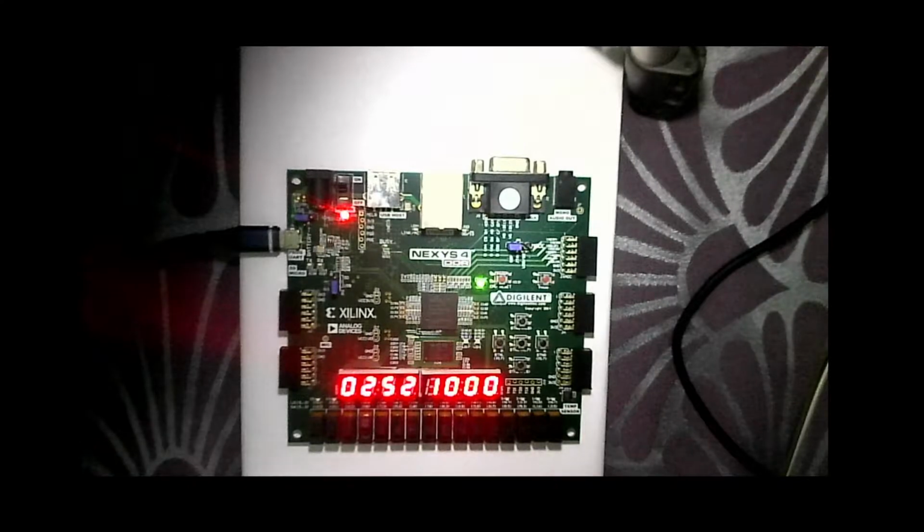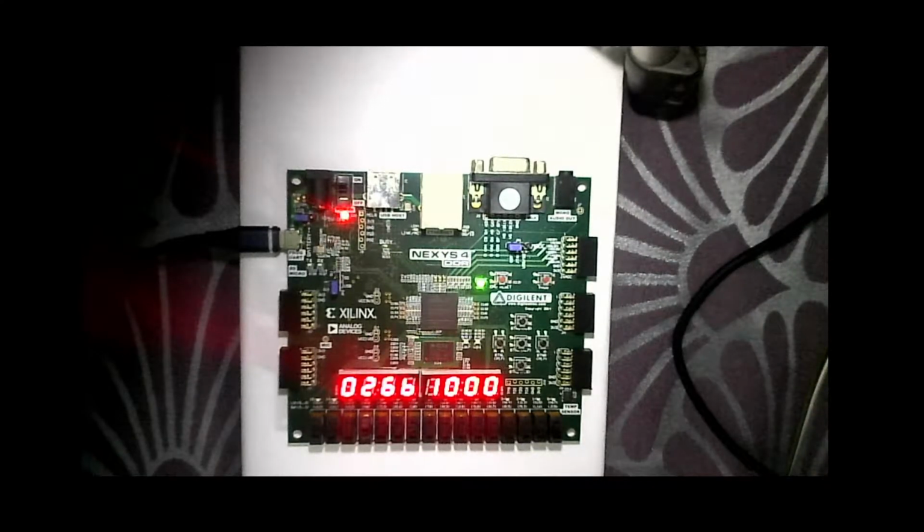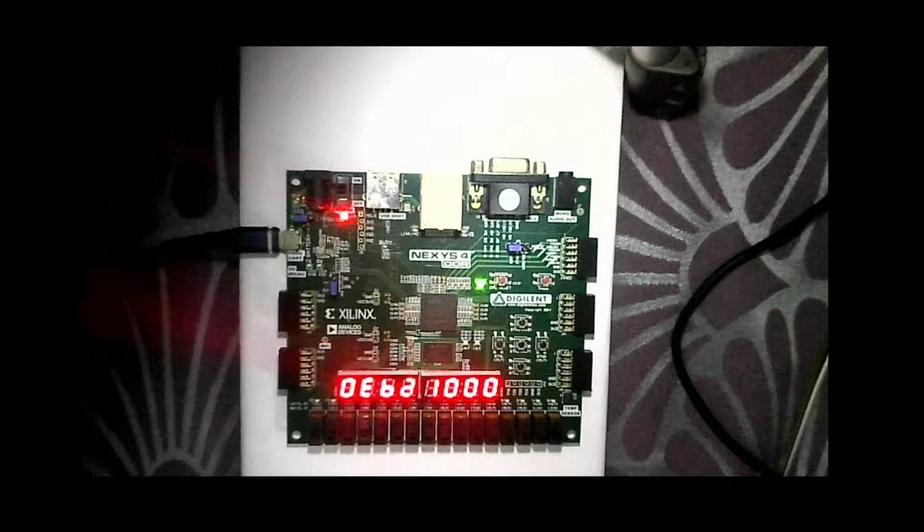It's a timer. Okay, so let me put you on pause for a second. Currently the count is this EC something, and I'm waiting for the moment it becomes FFF. After that there will be 1 0 0 0. At that point the counter is supposed to reset back to 0. So let's see if this is going to happen.